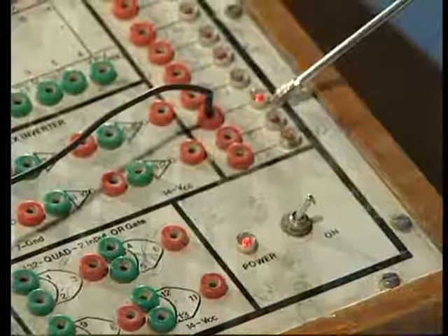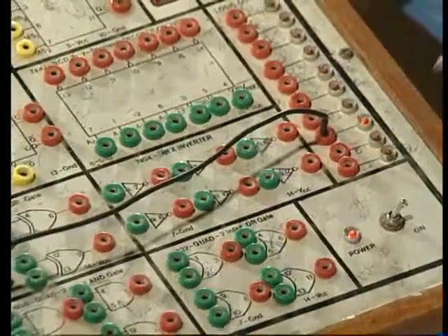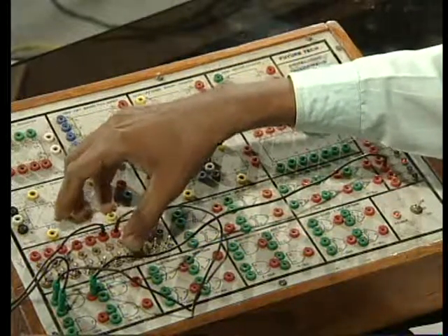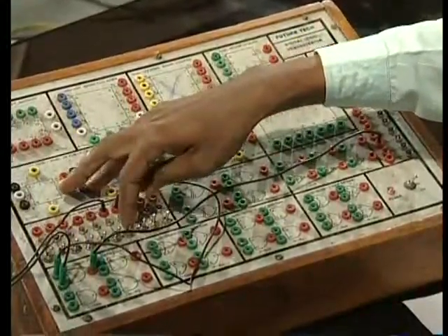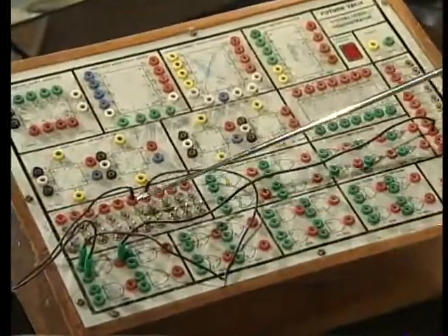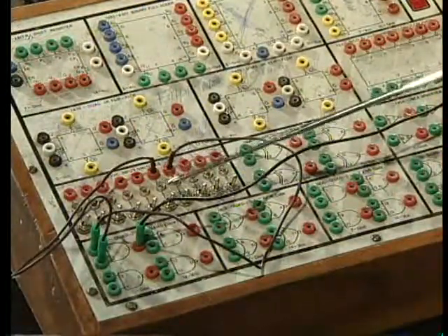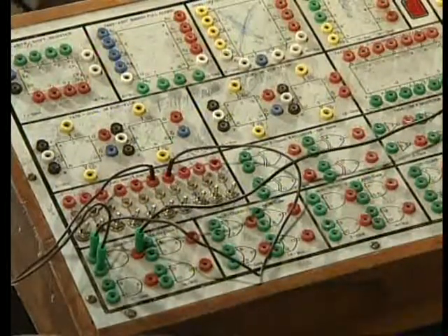The LED glow indicates a logic 1 and if it is not glowing, that indicates logic 0. Now, we shall verify various logic conditions of this 7400. Here we have applied the 2 inputs. This glow indicates a 1 and when the glow is absent, it indicates logic 0. Now, under this situation, both the inputs are 0 0. You can observe that the LEDs are not glowing. Under the 0 0 condition, the output of this NAND gate is logic 1.